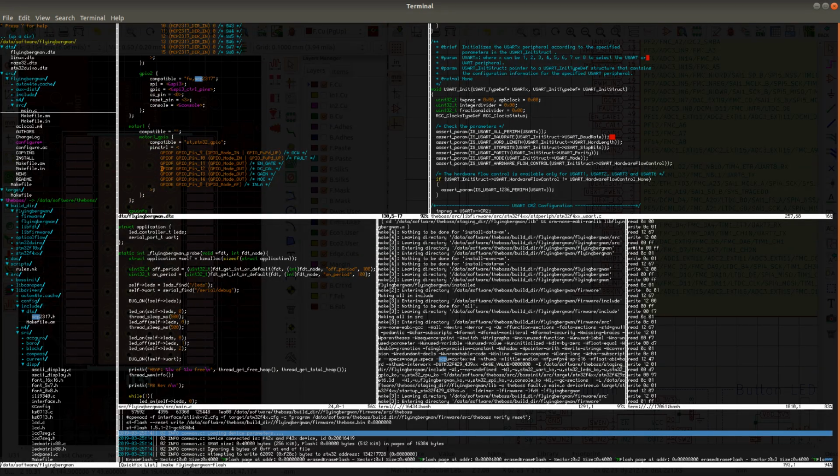use 2 megahertz. So the reason for setting the speed of the I/O is that if you really need high-speed I/Os, then you set 50 megahertz. But that setting affects the slope of the waveform that you're generating.